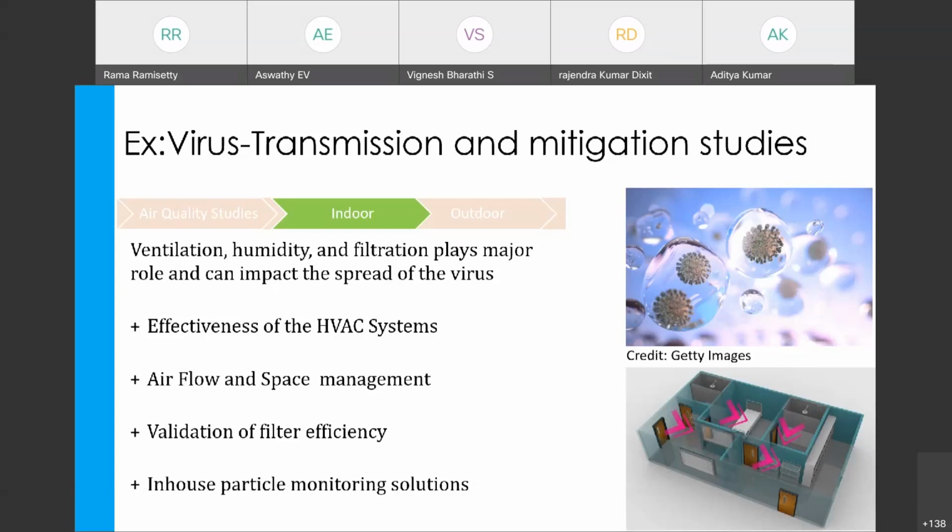They will stick to each other, and particle counting or mass measurements will not be accurate. So in that case, you have to use a humidity controller or temperature controller so that you can control the relative humidity and temperature of your sample. It's always between 40 to 60 that is the best range for aerosol measurements.